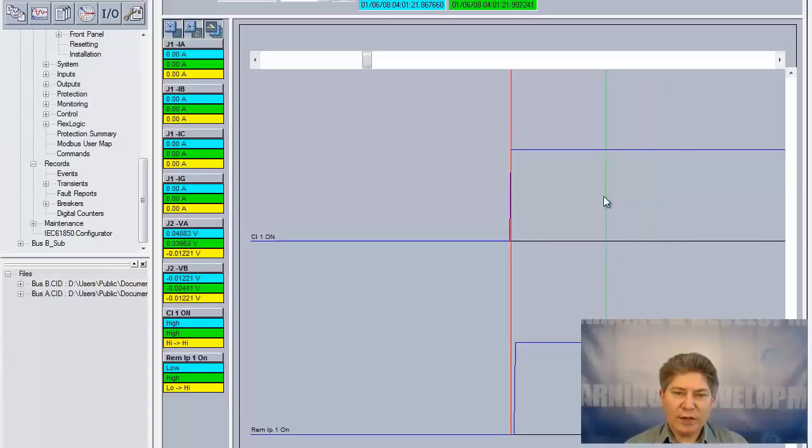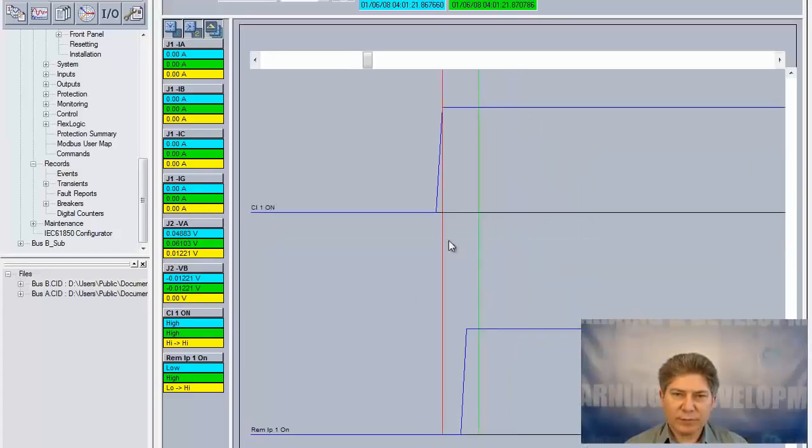The green line is showing our remote input that's been echoed back, and let's magnify it even further. So I'll make sure that underneath the red line is our blue line. It's used for measurements, and the return signal took 2 milliseconds, so there and back.